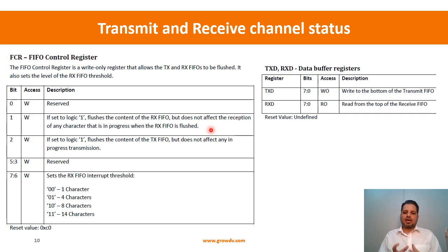So the way it works is, it has one register in which it keeps accumulating the serial data that is coming in. So that register won't get affected by this flush. So the total capacity will be whatever your RX FIFO is plus 1 extra entry.